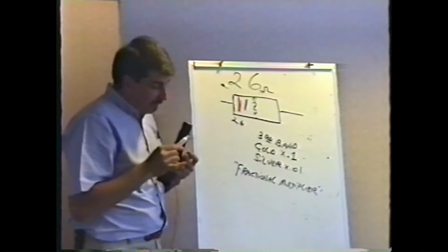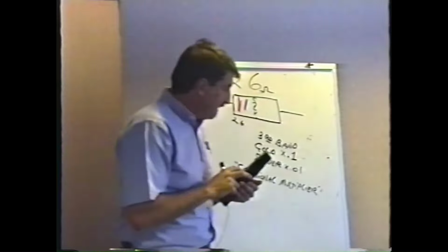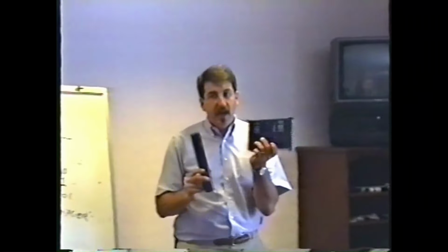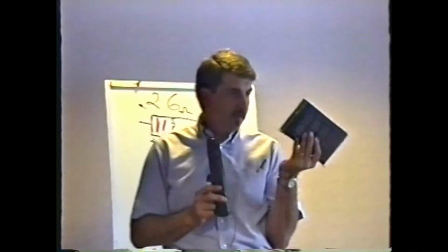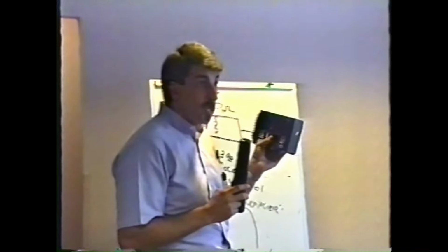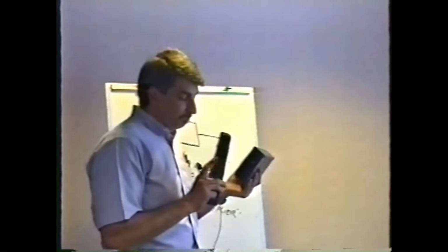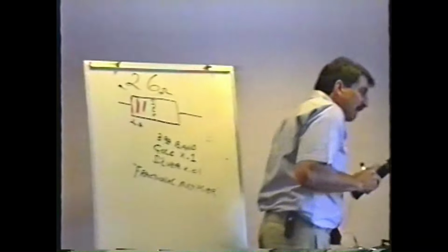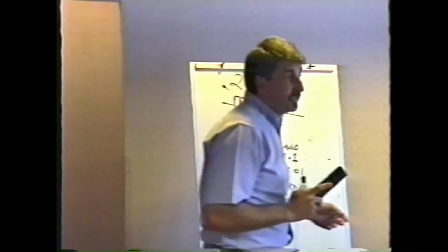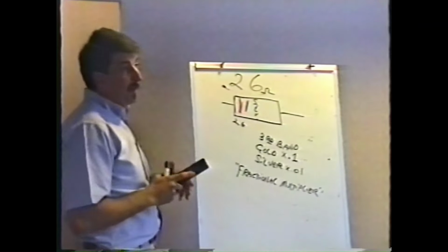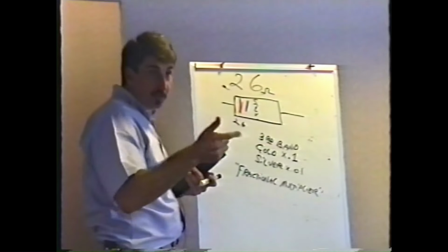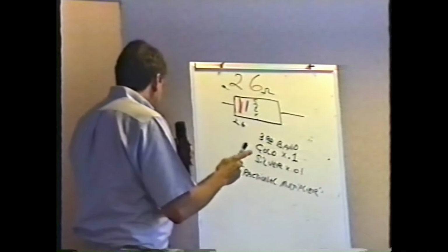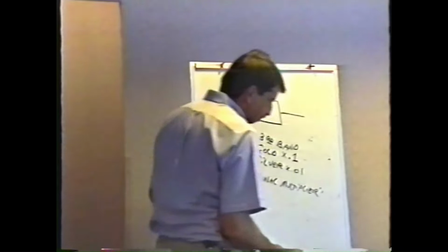The place that you commonly see these resistors is in these switching regulator power supplies, like these guys. There are some fractional multiplier resistors in here that you'll see when you open these things up on Wednesday. But that's how we get our values that are less than 10 ohms. The third band, instead of being a color telling you to add 1 zero, 2 zeros, 3 zeros, or whatever, instead is gold or silver.